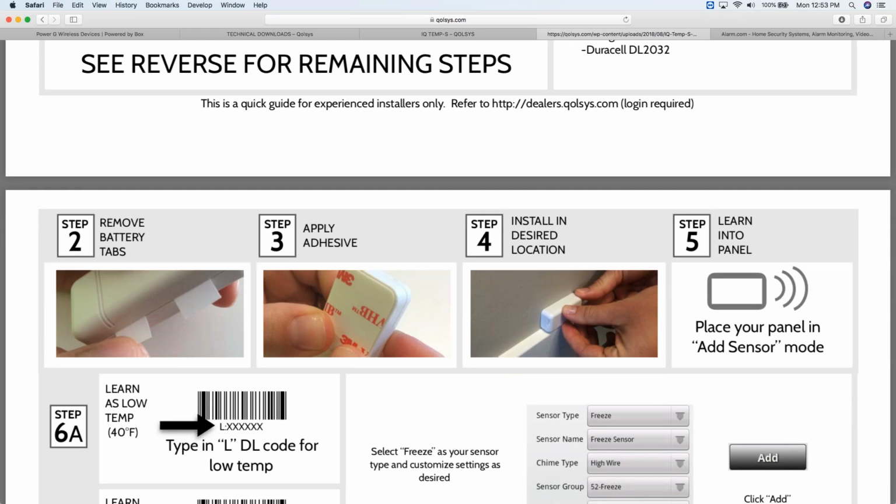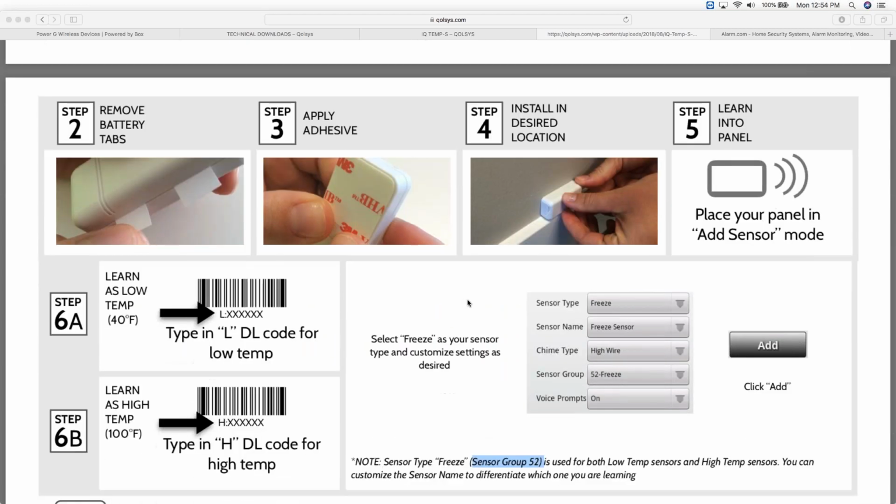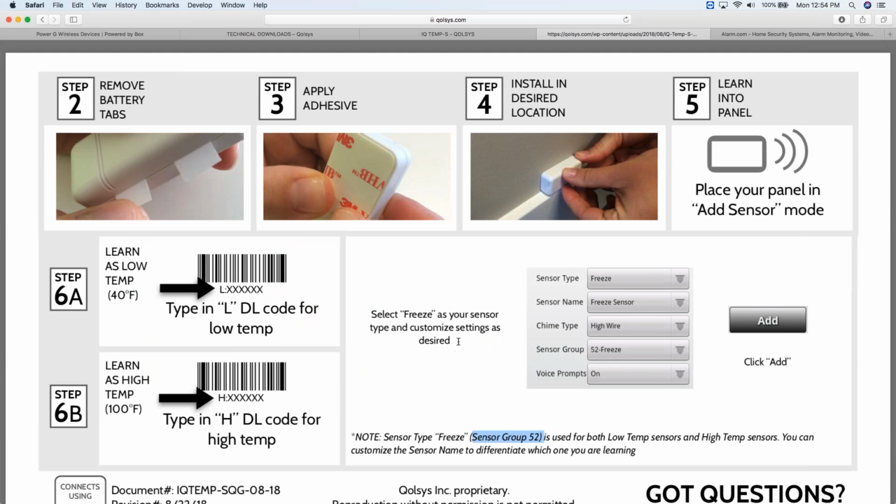Great question. I got another question here. How many 2-wire smokes can your hardwire converter use? So I mentioned that our hardwire translator is now fully certified and listed to take over 2-wire smoke detectors. That will support up to 10 smoke detectors wired together.